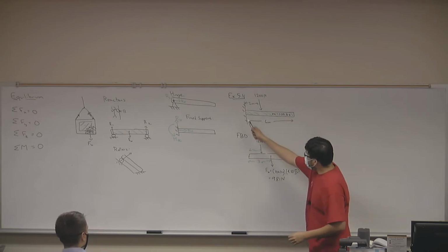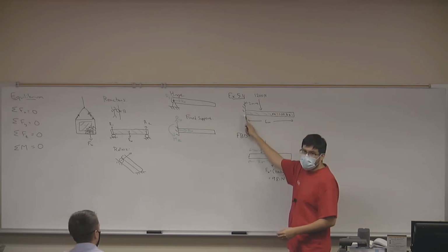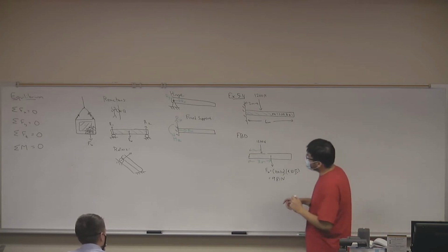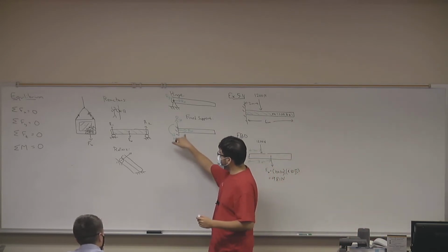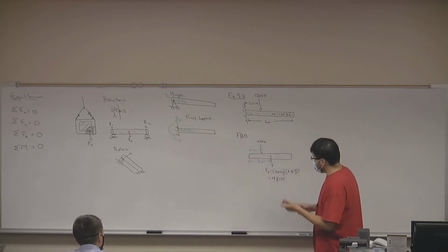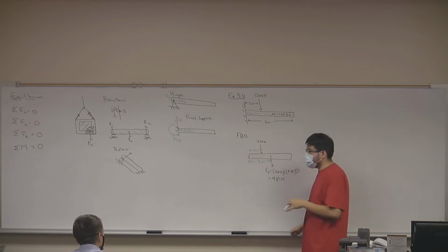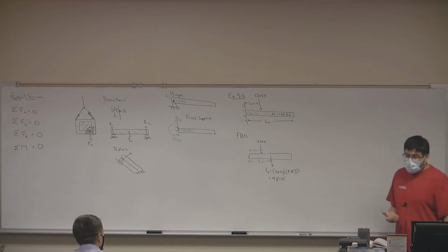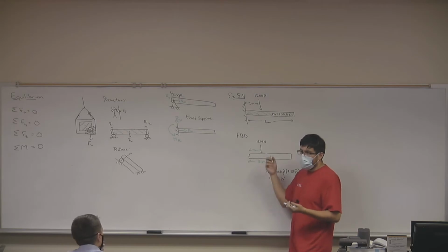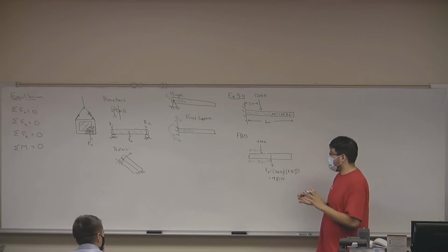Right now, this beam, as you can see from the diagram, is supported at the left with the wall. What type of support do you think this is? Fixed. Okay, good. What that means is that a fixed support will provide us with an X reaction, a Y reaction, and a moment. So we will have to consider an X reaction force, a Y reaction force, and a moment. Now, it doesn't matter if you decide that the X reaction force is in one direction, the Y in another, because if you assume incorrectly, you'll get a negative answer. So I wouldn't worry too much about that.